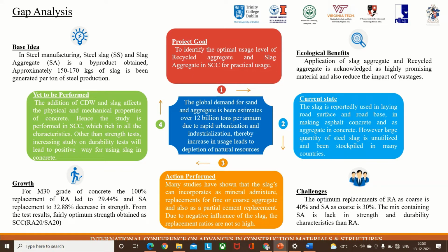The challenges we have faced are that the optimum replacements are not so high for recycled aggregate and slag aggregate as coarse aggregate, at 40% and 30%. The mix containing slag aggregate lacks strength and durability characteristics compared with the recycled aggregate.